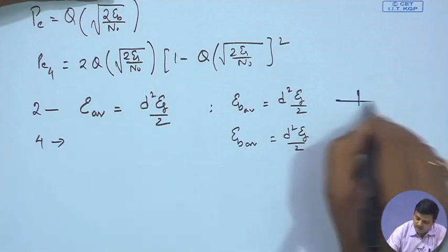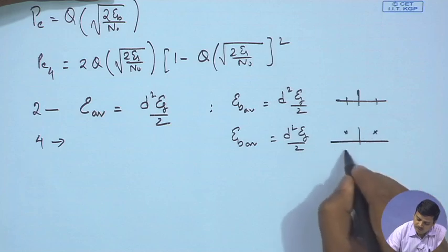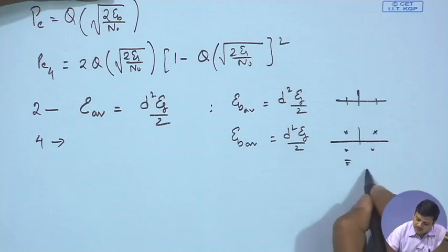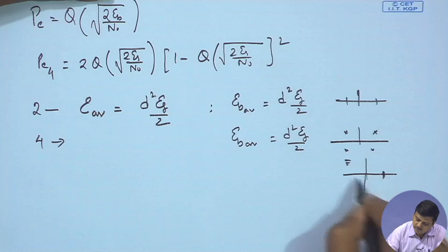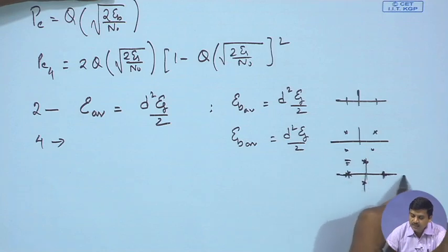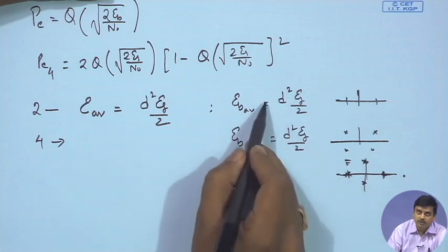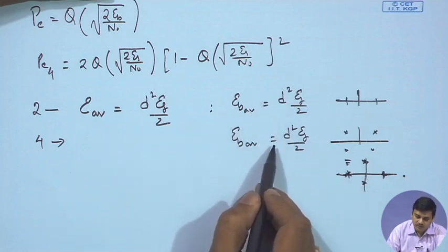That means, here we have BPSK, here we have QPSK. This has an equivalent form in terms of constellations here. So, you can imagine this to be BPSK or binary pulse amplitude modulation on the I channel and Q channel, and hence the performance of BPSK and QPSK would be similar.